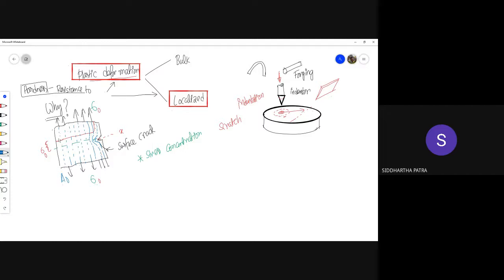For the region where the curvature has vanished, the stress is the nominal stress. But if you zoom in closer to the crack tip, this is what is happening: all of the boundaries of those segments which carry equal loads have concentrated in the vicinity of the crack tip. The next line would essentially pass through this.